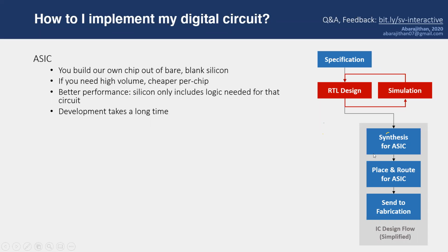Once you finish this, that is, you design your circuit and it becomes HDL code, you take the code and there are different tools, different software, say the Synopsys tools. They take this and do the synthesis. Synthesis means they translate your code into a different code, and in that code you basically have flip-flops and AND gates and OR gates and everything, very primitive things.